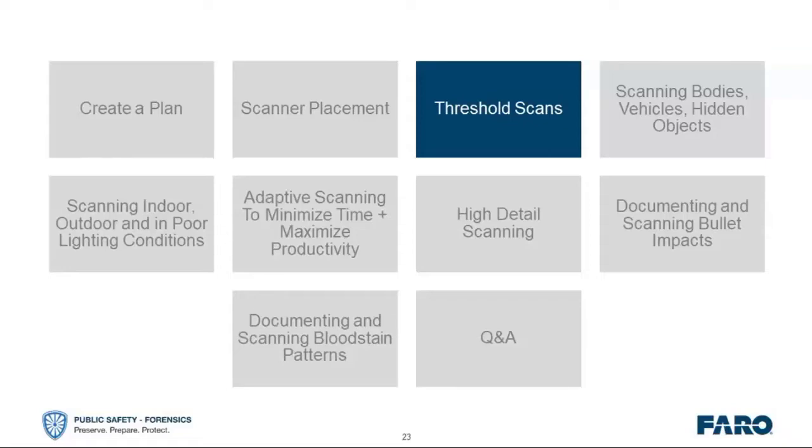Threshold scanning will allow you to scan the interior of a structure in a desired high resolution and high quality setting. And the door is closed. Open the door, scan it in the threshold. When I say in the threshold, right in that door frame. Just put it right in that door frame. But change your settings. I prefer very low resolution, like a 1/10 at least.